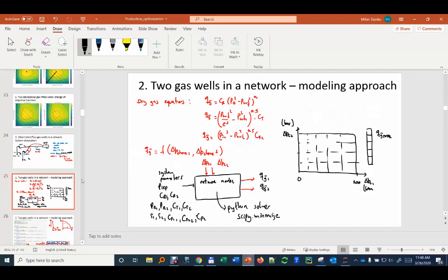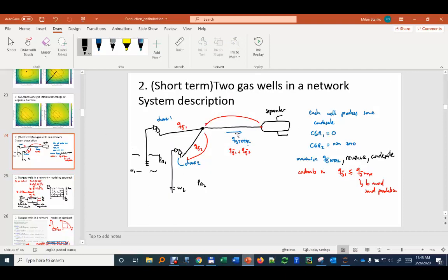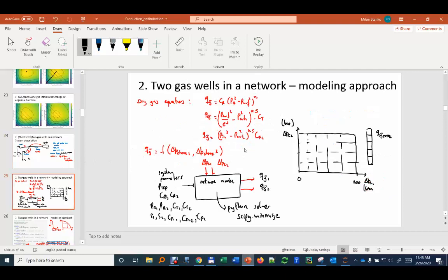So then I say, how do we solve this problem? First, we look at the model. We said we're going to use dry gas equations for all the parts of the model, and the model we can visualize like we gave all model parameters, and here we need, besides that, N1 and N2, for the inflow, IPR, tubing, TPR, we have the flow line, and then we have the pipeline.